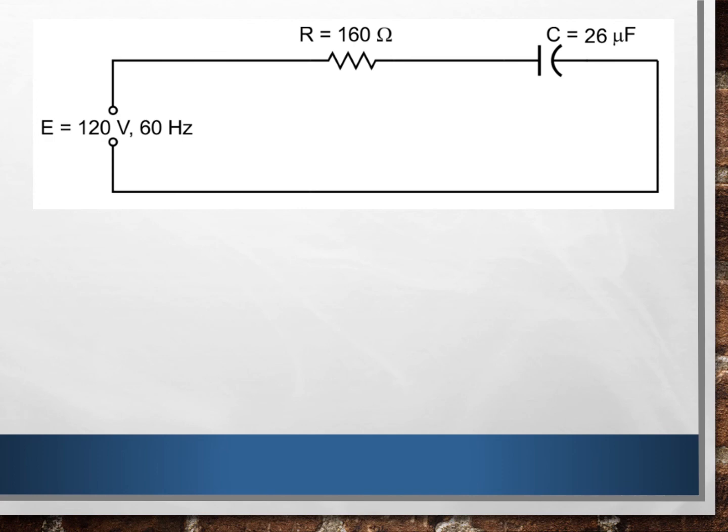All right, so we have our capacitance. The next thing we need to find is our capacitive reactance. I'm going to use my formula. Xc is equal to 1 over 2 pi Fc times 10 to negative 6. The 10 to negative 6 automatically converts it from farads to microfarads for me. So since my capacitance is in microfarads, it's going to give me my ohms in the right value.